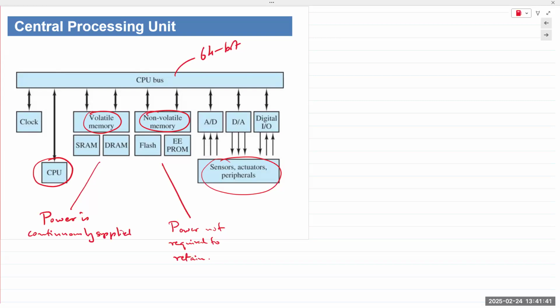Okay, but RAM, however, does not stand for read-write or volatile or non-volatile. RAM stands for random access memory. It actually has to do with the description. It actually describes the manner in which the stored memory is accessed. Okay, so typically memory would be accessed in a sequence or in parallel, right? So if you have an 8-bit register, it stores 8 data bits. If it's a serial fashion, the data comes out bit by bit.